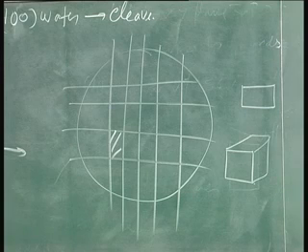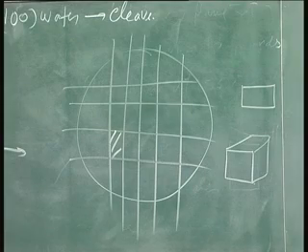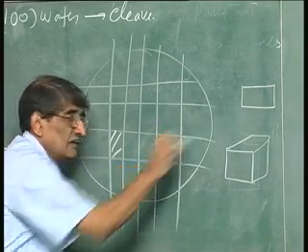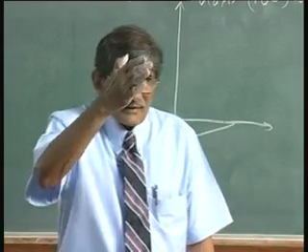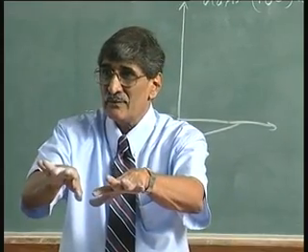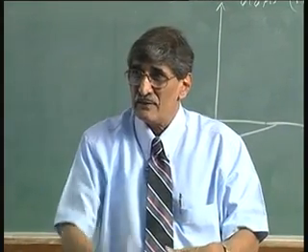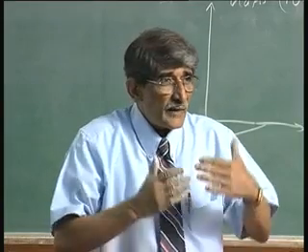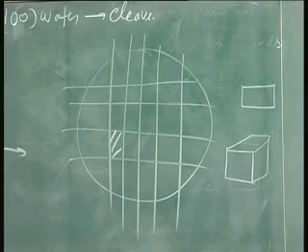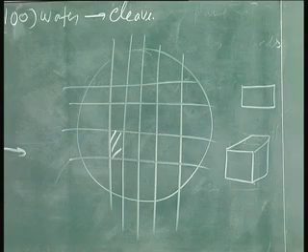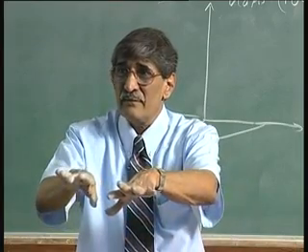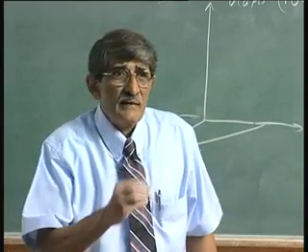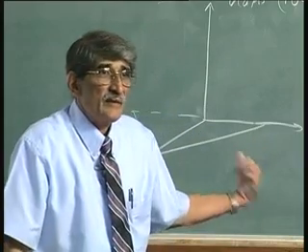Now, you may ask, what do we care? Why should I worry about that being vertical? In microelectronics, you may not worry, because in microelectronics, what all that happens is here. But when you go to make a laser, you want that plane to be where the light is coming out, that should be polished and to be vertical. So, when you want to make lasers, this cleavage plane which is perpendicular to 100 helps you. In fact, you can have those surfaces which are shining and which is giving that laser in that plane. So, for making laser diodes, this property is very useful.